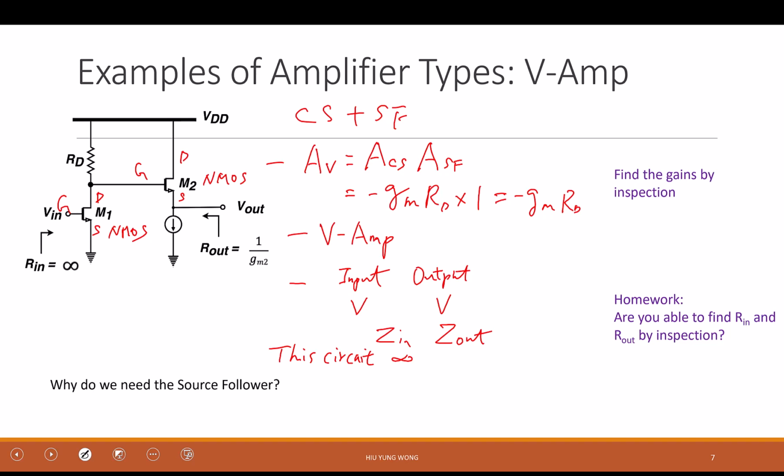What is the output impedance of this circuit? Going from the source of the transistor to the drain, so it has to do with that. It goes into the source of the transistor, so it has to what? 1 over gm2. Yeah, some of you are laughing, because it is up there. But that is great that you explained. You did not just tell me 1 over gm2. Is this okay?